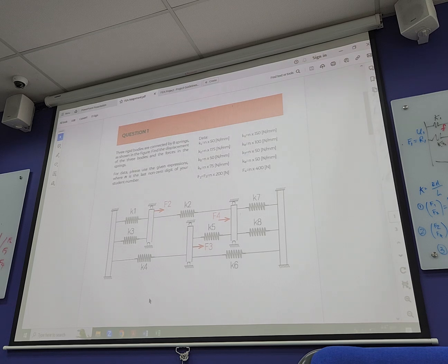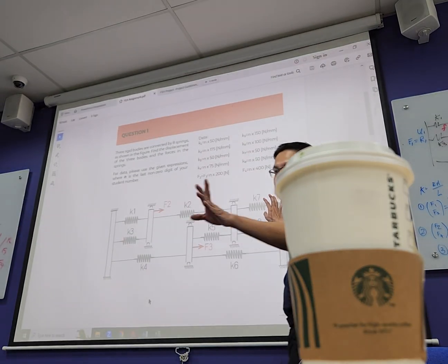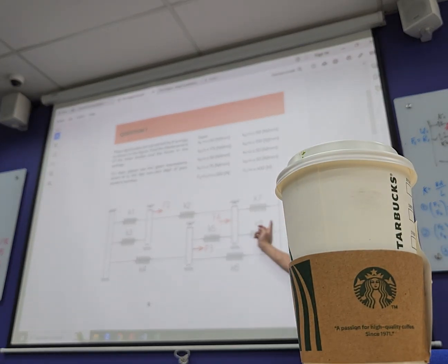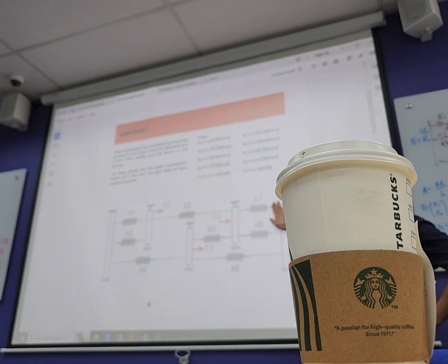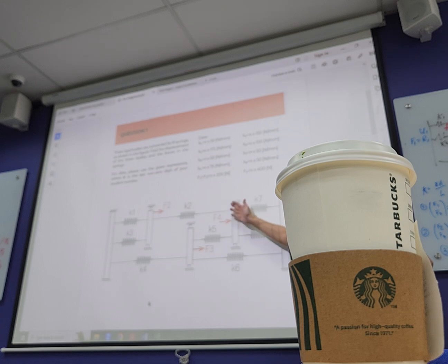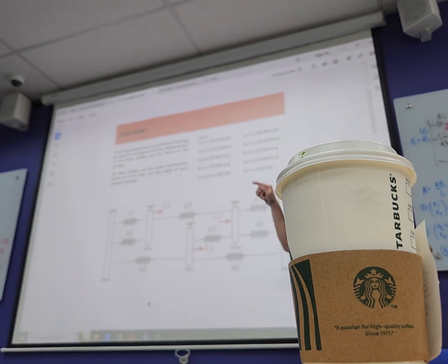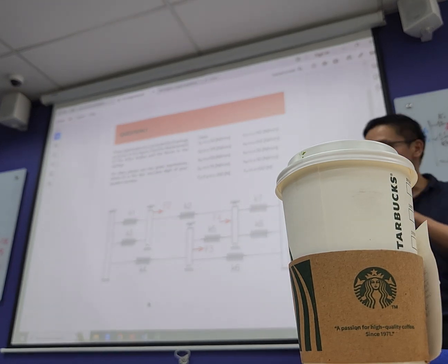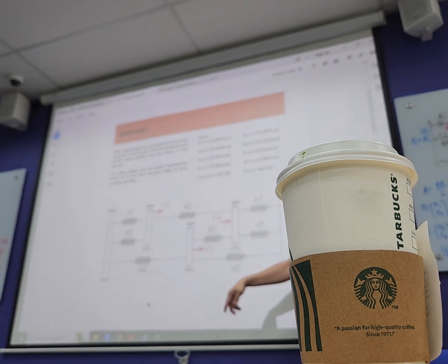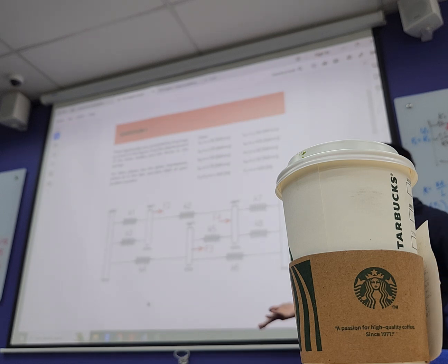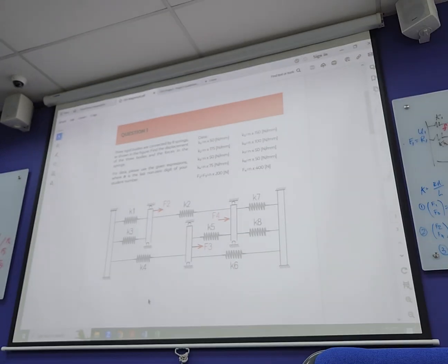This question was raised, which I thought was very good and illustrates your understanding. Imagine this element here. U5 equals 0. If you have a positive U4, then it will be U5 minus U4, so you get a negative U4 multiplied by K7. It shows that for a positive displacement in U4, you will have a negative force in K7, which is a compressive force. Make sense? Good.